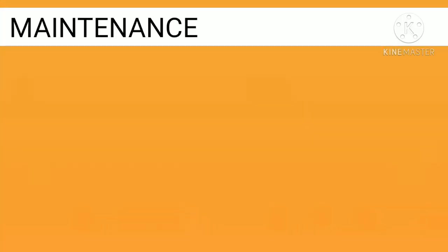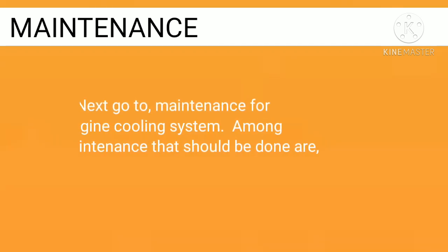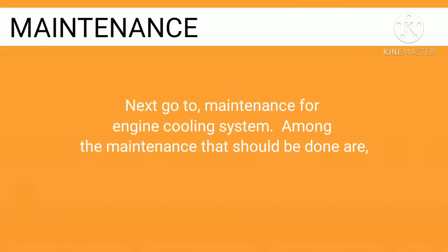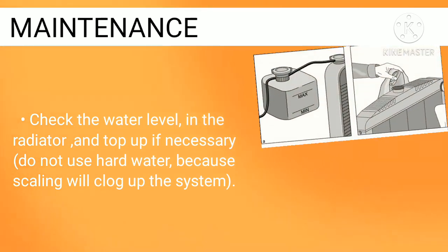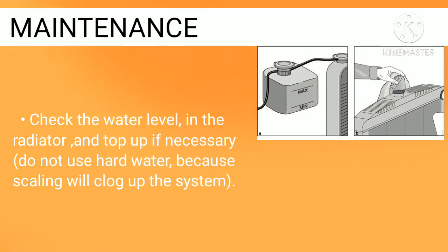Next, go to maintenance for engine cooling system. Among the maintenance that should be done are: check the water level in the radiator and top up if necessary. Do not use hard water, because scaling will clog up the system.